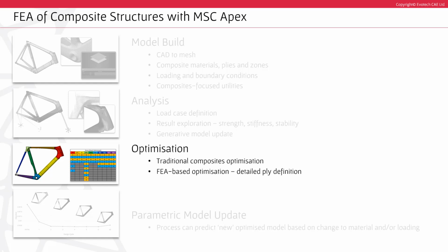So in this example, we're going to be focused on ply-based sizing, which allows us to look at things like material selection for our ply generation, or applied materials, maybe UD definition and woven cloth definitions, our orientation, so how the fibers are oriented over a given structure, and then the thickness and the number of plies that we might want to specify within the region.